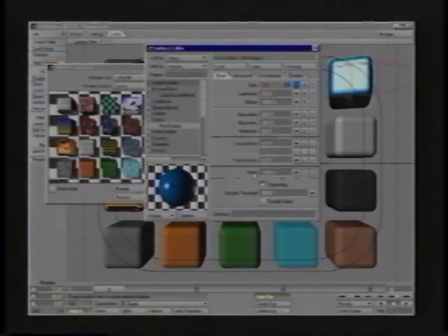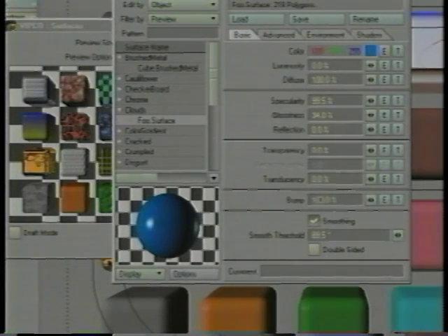The next setting is bump map, and bump map is not too interesting until you actually add a texture, so we're going to hold off on talking about bump maps until we explain the texture editor itself. So we'll go ahead and go down here to smoothing, and smoothing is basically a way to make rough geometry look more smooth along its contours. When you're working with polygons, you're always going to have little stepped edges to get from one point to another around a smooth surface. So smoothing will do a surface trick to smooth that out.